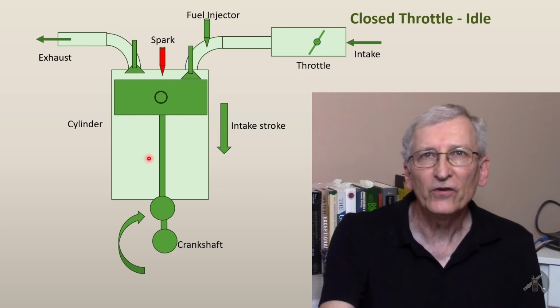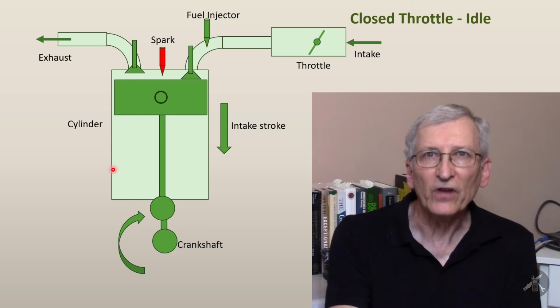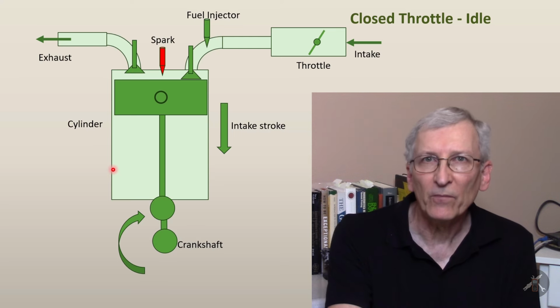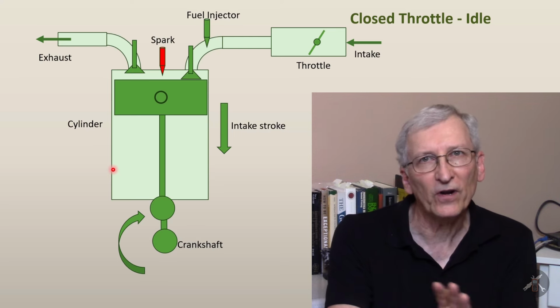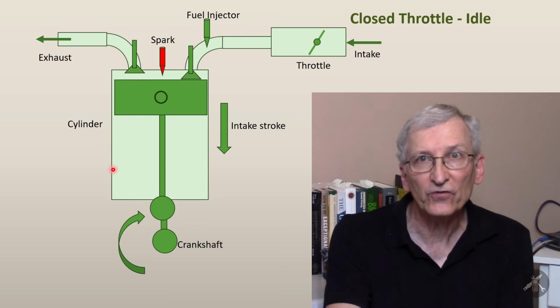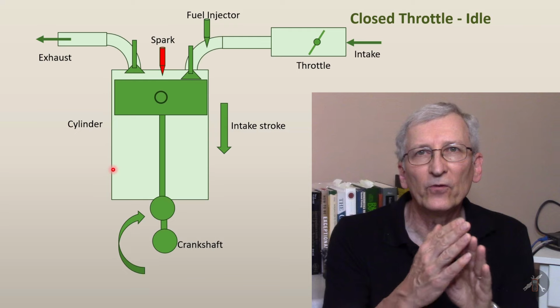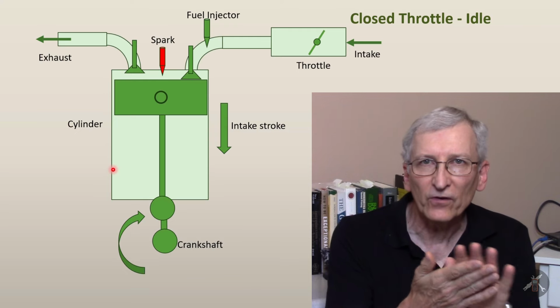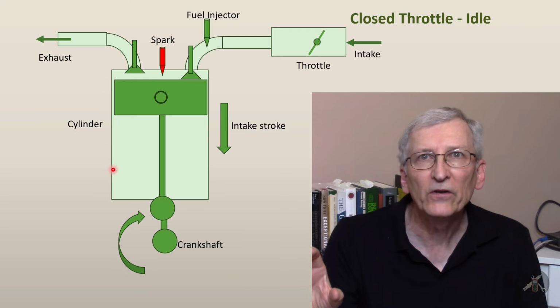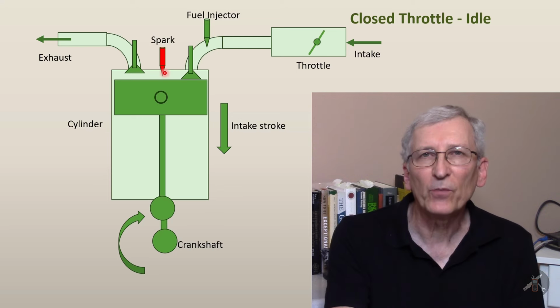Not a very good situation. So the whole point in a gasoline engine, a standard internal combustion engine, is that you have generally a homogeneous charge. I know there are stratified charge engines, but typically you bring in air and mix it with fuel, and the fuel-air mix should be consistent, equal, and well blended, so that you get a good ignition at the spark plug.